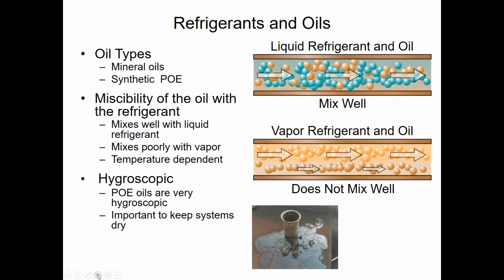So again, as I mentioned a little bit earlier, one of our big concerns with sizing pipe is not only the refrigerant velocity and your actual friction loss through the piping, but also oil return. Oil with liquid refrigerant in our liquid lines, the miscibility is great. We have no problem entraining the oil through the system in the liquid line. It's when we get into our vapor lines, our suctions and our discharge lines or our hot gas bypass lines, that's where we start getting into trouble and need to be spot on with your pipe sizing.